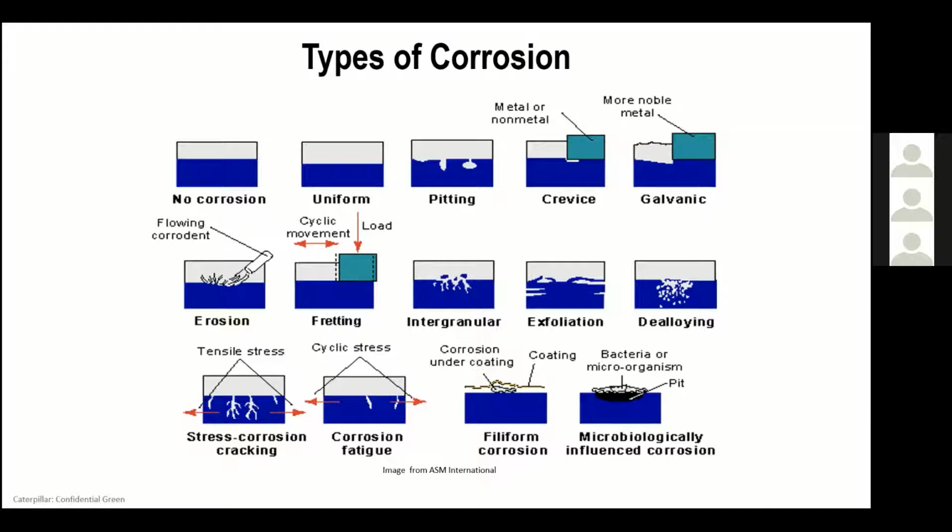Fretting, that's a cyclical movement on a load. And then people that we work with that are material scientists, they get involved in looking at the metal and below the metal. And so they'll look at how the grains are actually impacted. And so, is it granular, intergranular type of corrosion? I'll show a slide here for what a material scientist works on, but they'll use technologies like the scanning electron microscope and really try to look at failure.